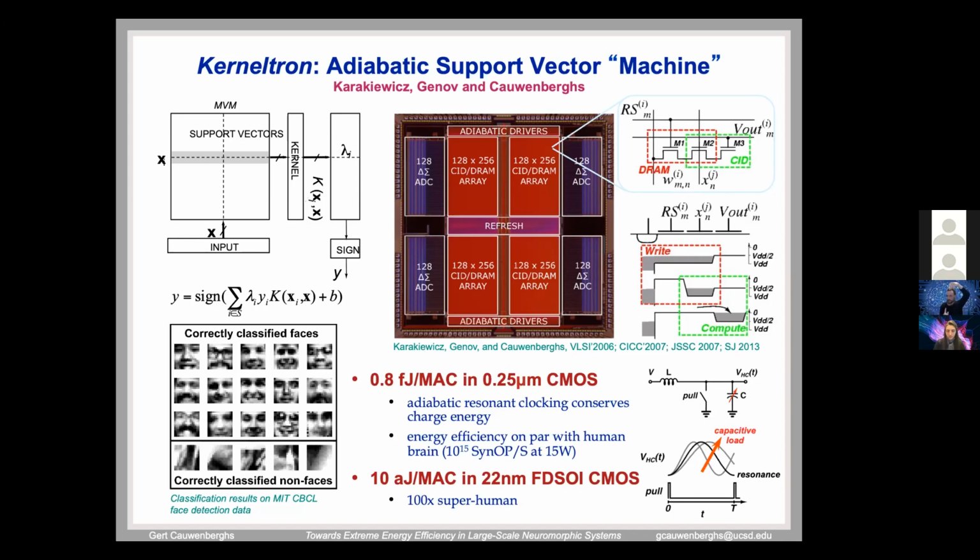If you use a CMOS switch that way, you have a PMOS that pulls you up and an NMOS that pulls you down. So in one cycle, up and down, the charge has been delivered from VDD to ground, and the entire energy is wasted, the entire potential has been wasted. That VDD times charge, which is C times VDD, so basically C times VDD squared, has been wasted.